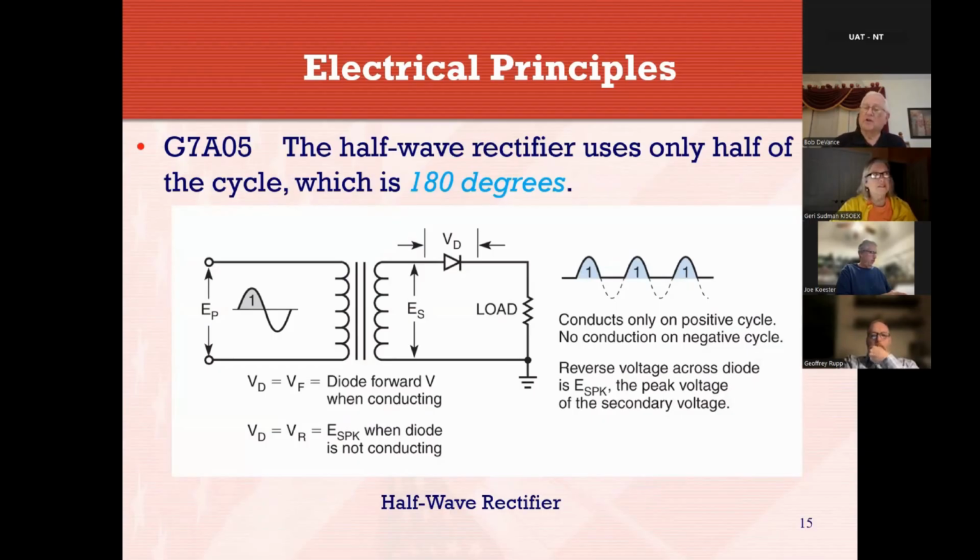Talking about rectifiers there. Yes, go ahead. I had a question, more of a statement. I was told that the linear power supplies don't put out as much RF noise, or are quieter. Yes, the linear power supplies are great in that they don't generate RF. The switching power supplies use a high frequency oscillator to convert the AC down to DC where we want it. They do use high frequency oscillators, and those do generate RF interference.